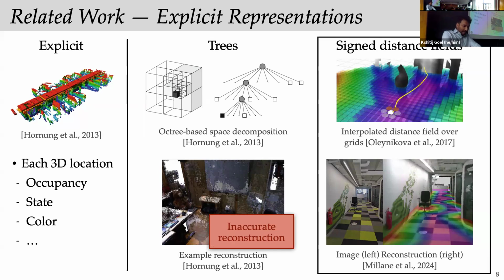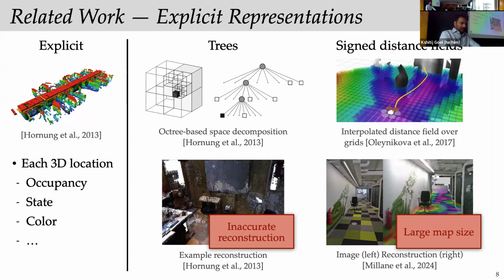Towards achieving more accurate reconstruction, truncated signed distance fields have been used in practice. The idea is to maintain a TSDF over time for accurate surface reconstruction, and then interpolate a distance field for robotics applications like collision avoidance. Unfortunately, the map sizes are quite high in this case, since the cell size has to be kept small in order for the interpolation to work well. In a nutshell, there's no sense of compression in 3D space for these approaches.